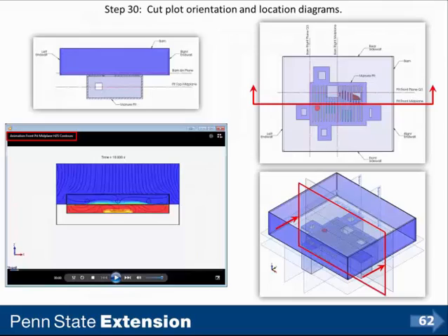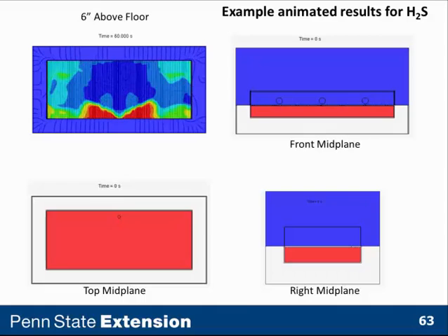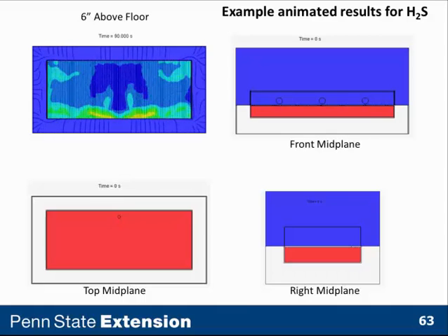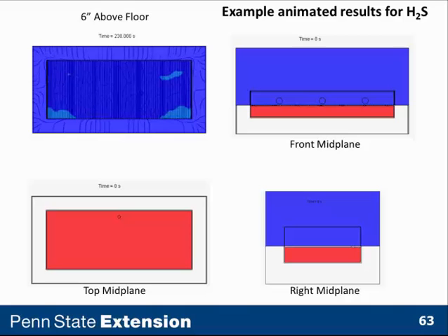Let's go back and view that again. You see we have some pretty large portions that are red, light green, and certainly pale blue, and those would be problems of concern. But after 280 seconds, the whole domain is all blue and all okay. So for the conditions of this design example, this case study, we'd probably have to evacuate all of that building before we would dare ventilate it.